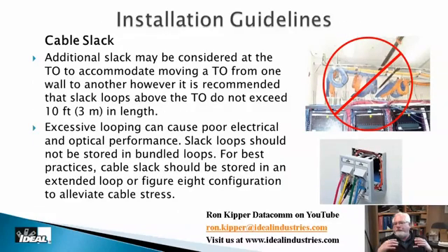Now, as speeds and frequencies keep going up and up, today we're telling you that that's not a very good practice, because that 100 ohms I talk about, that impedance, has three factors. One's called inductive, one's called resistive, and one's called capacitive reactance. Actually, capacitive reactance is the big one, but one is inductive reactance. As you coil that cable up, those magnetic fields are adding up, and you're changing what's called the inductance in the cabling, which is affecting that 100 ohm thing. So that's why they tell you don't do this anymore.